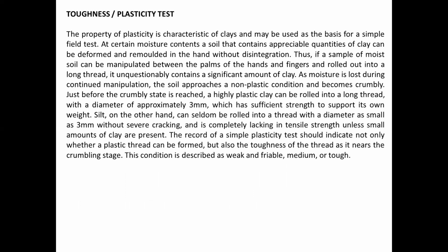We have now the toughness or the plasticity test. The property of plasticity is characteristic of clays and may be used as the basis for a simple field test. At certain moisture contents, a soil that contains appreciable quantities of clay can be deformed and remolded in the hand without disintegration. Thus, if a sample of moist soil can be manipulated between the palms of the hands and fingers and rolled out into a long thread, it unquestionably contains a significant amount of clay.